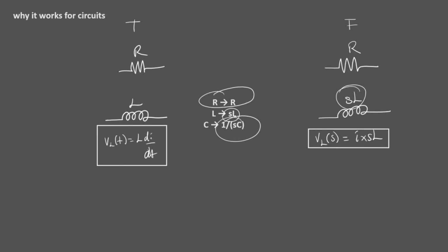It's related to the Fourier transform, etc., but we'll get into that in later videos. This is just to get a background of what happens. So we are trying to go from complex differentiation, complex integration, right? Where you have d over dt, you have a multiplication by s, and where you have an integration, we have a division by s. This is what we're trying to do when we work with the Laplace transform to make RLC circuits easier to solve. All right, so in the next videos, we're going to get into more mathematical expressions, get into derivations of all of this, then bring up circuits and solve problems.